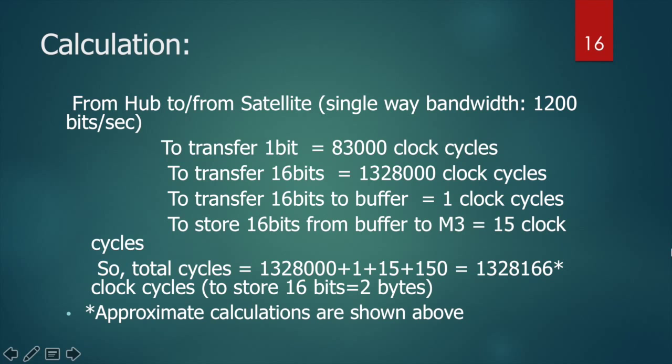The same thing happens for device to receive data from the satellite. When the device provides a command to receive 1024 bytes, say for example, if the memory is full in the hub controller, then a 32-bit command is sent to the satellite and data is received from the satellite based on the sat command control register. The control register gives the tag info of the memory whose data needs to be moved to the satellite, the tag info of the memory where the data from the satellite needs to be moved, and the total bytes that are to be moved between satellite and memory.